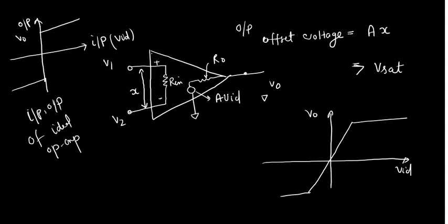It's the slope. For ideal scenario, it should be something like that. Good. So even if your X is very small, you will reach saturation. And in practical scenarios also, this is very steep, very steep. So even if your X is in microvolts, you have seen this in one of the numericals, right? So your output offset voltage can be assumed as plus minus V sat. Okay?